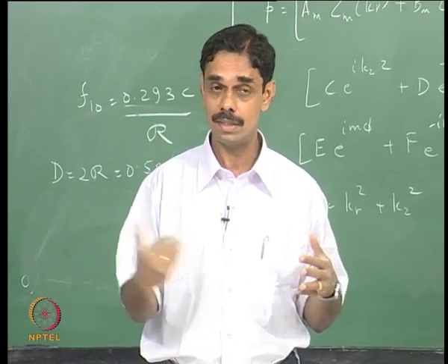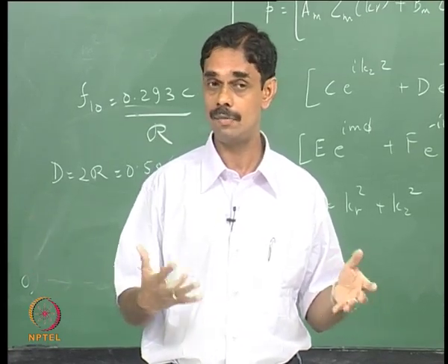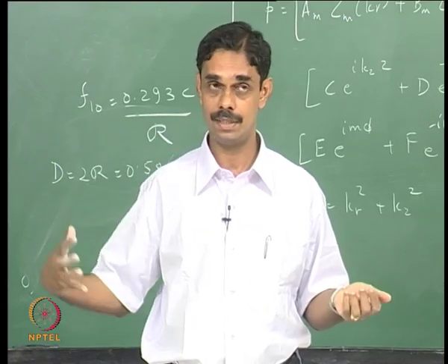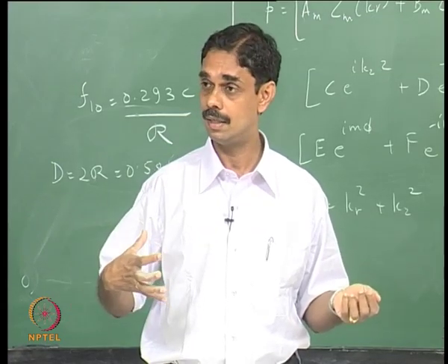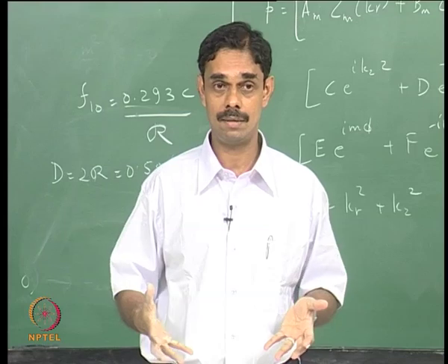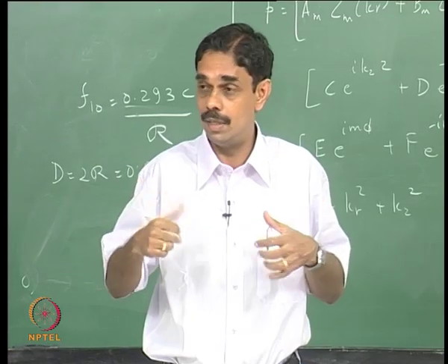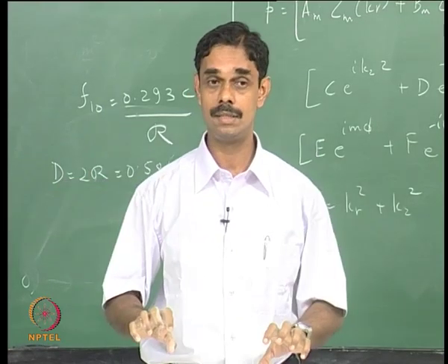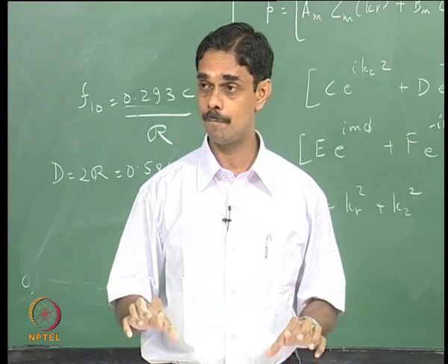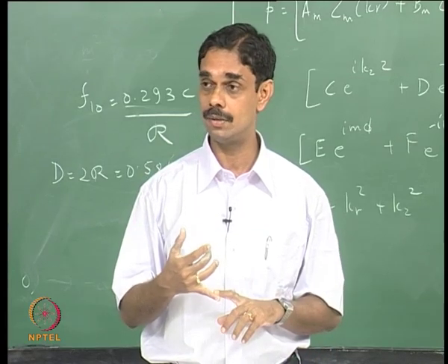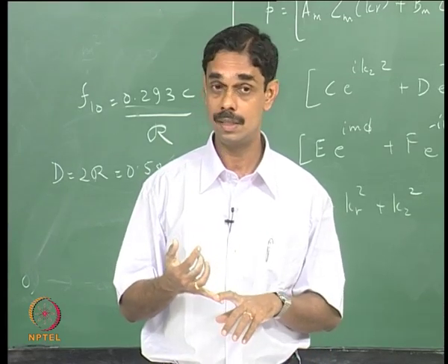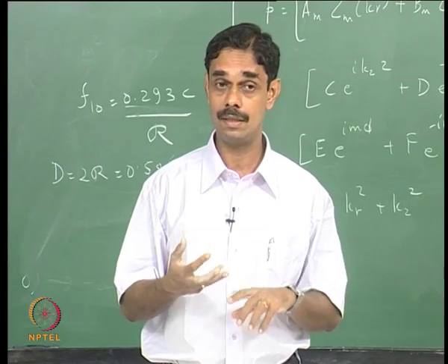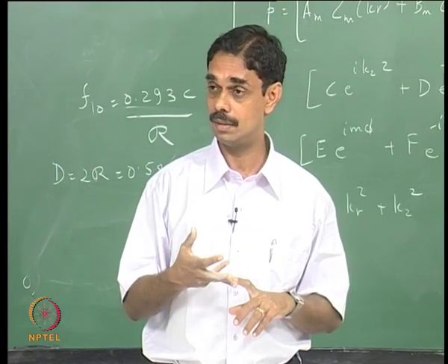So we linked admittance to the energy flow, and that we linked to growth or decay, because if energy is coming in from the boundaries, your acoustic energy in the duct will grow. If the energy is going out, your energy will decay. And then we looked at sound propagation through regions of non-uniform temperature, then attenuated waves and so on.